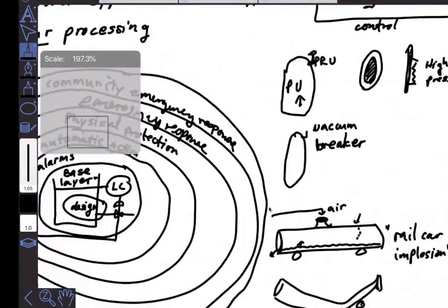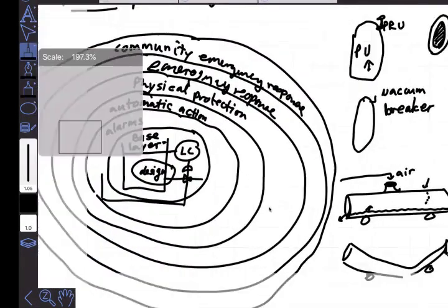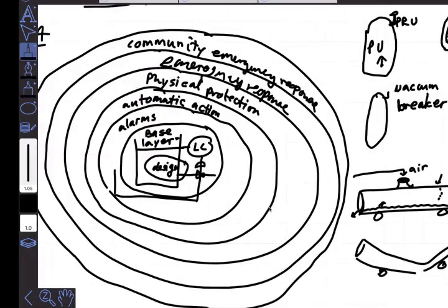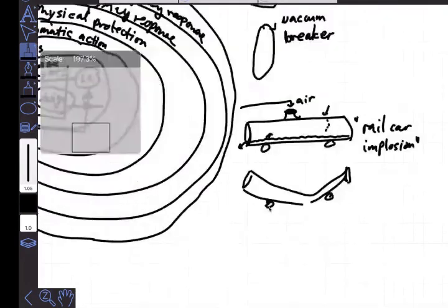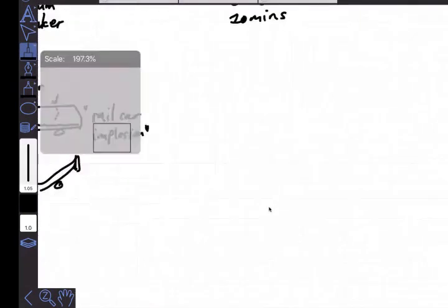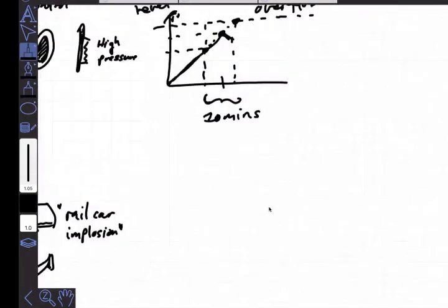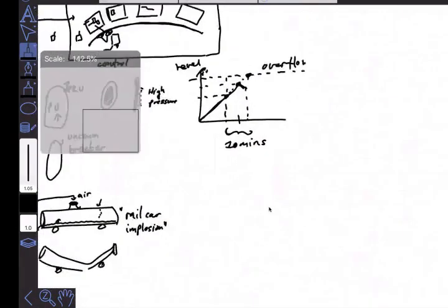But there's a very distinct reason why this happens, and it's a little bit due to the way that software works. These days, the way that you build these alarms is not by purchasing an actual physical alarm. Typically, you'll have an alarm that's set up within 90 to 10% of the full range of the measurement instrument. And those defaults get dragged and dropped onto the flow sheet. So there are two important things that we've learned from the way that people set up sheets.